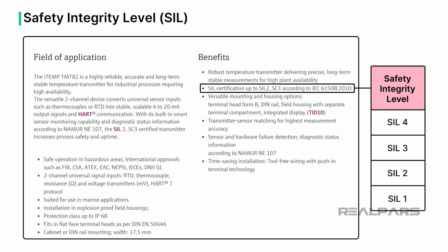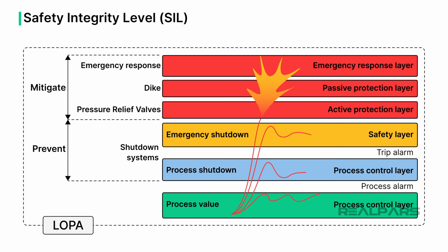Alright, so how are the SIL environment requirements determined? In a nutshell, each hazard is assigned to a target SIL. The determination process involves hazard analysis and risk assessment to bring the overall risk to an acceptable level. Not every company uses the same determination process.